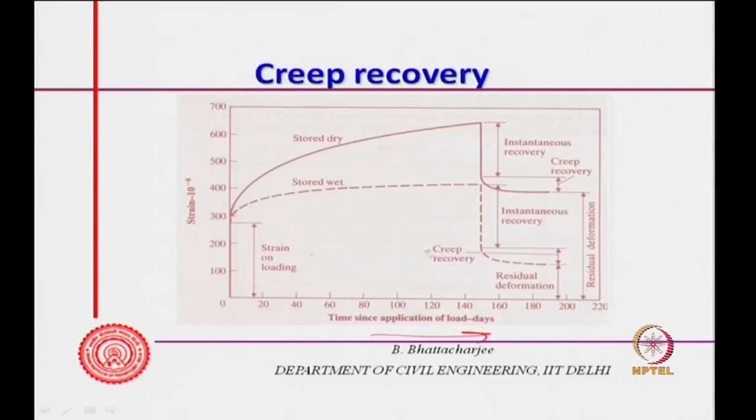So, this is time since application of the load, this is your T, and I withdraw this stress. Now, what I find is the strain comes down, but then it does not come back to the 0 level. I have applied stress, this is the elastic strain at sigma 0, then this is the creep strain, and then I just withdrew the load completely.